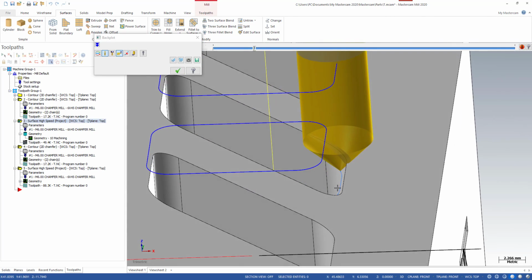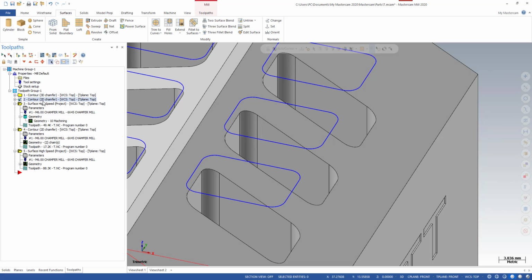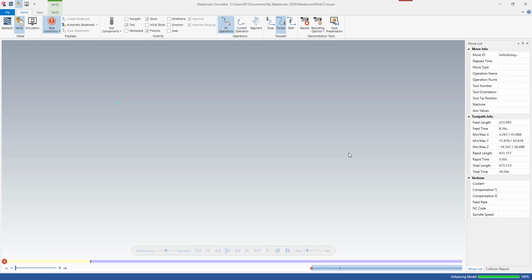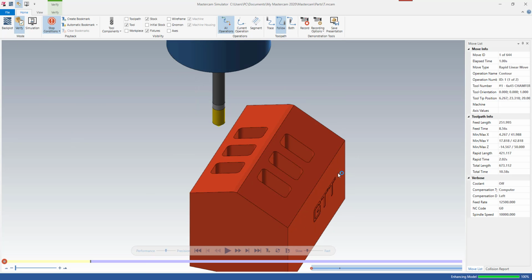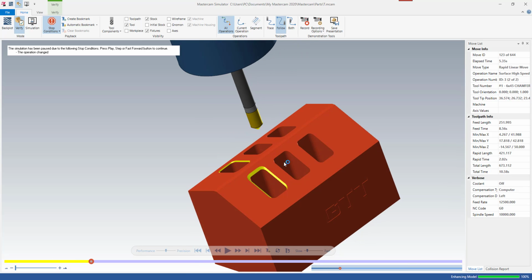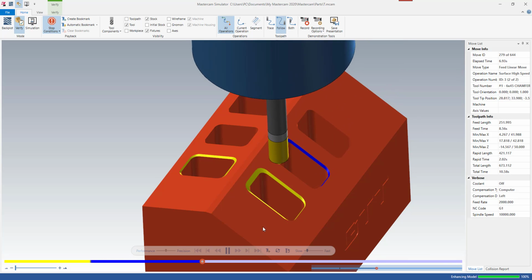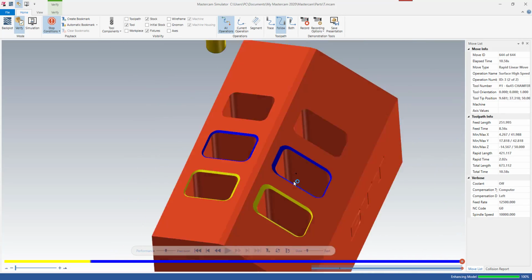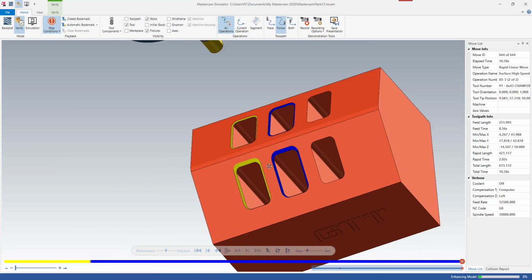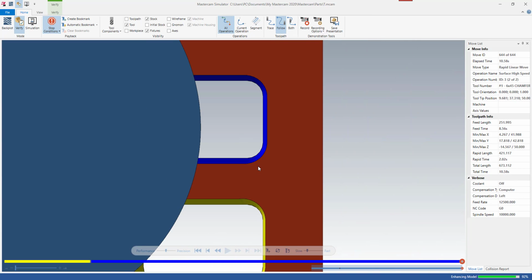You can see this is how it works, and we go back to see the result. You can ghost this toolpath, so make sure it's going to be positive. Okay, so I just verify these toolpaths, the 3D chamfer and the project toolpath. So this is the 3D chamfer. And this is the project toolpath, and this toolpath is projected from a 2D chamfer. Let's see if we have any difference. You can see that we don't have so many differences. When I look from the top, just a little difference.